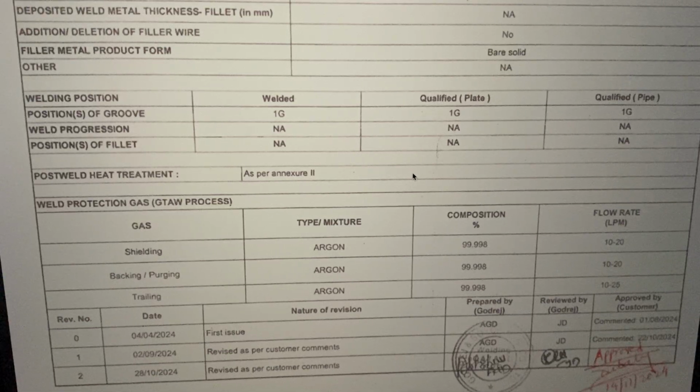Then comes the gas, in case we are using a gas or a flux. What flux type are we going to use, and how are we going to do the shielding? Is it the primary shielding? What diameter of ceramic nozzle are we using, what diameter of CO2 nozzle are we going to use, or if it is a gasless wire, what diameter, and what is the recommendation by the manufacturer for this? If we are going to use mixed gases, how are we mixing it?